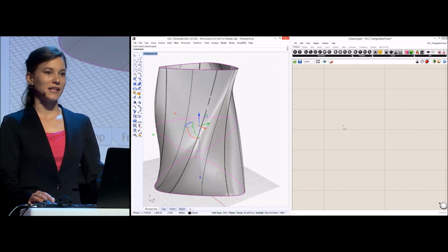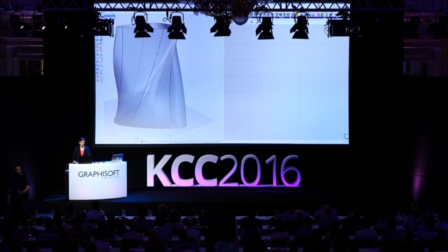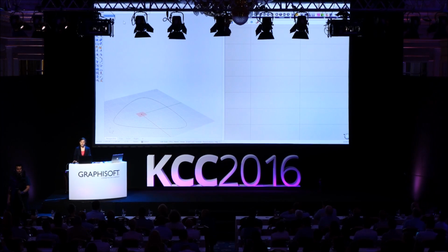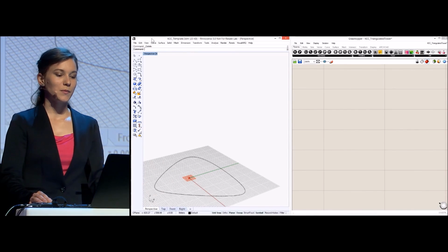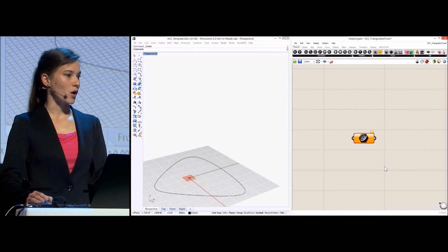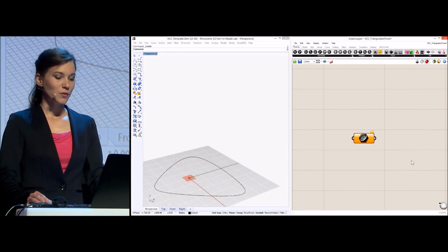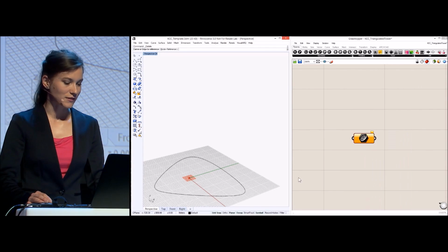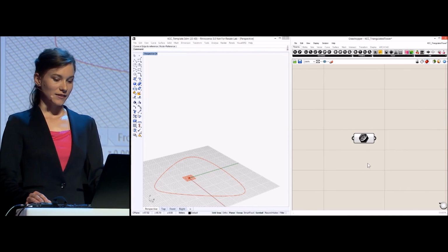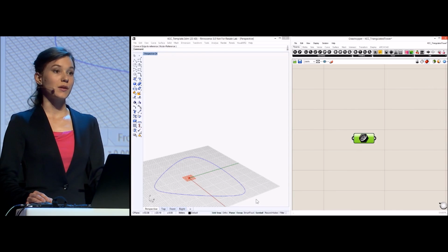Now, for those who are not familiar with this design environment yet, let me give a short intro. As an example, I will recreate the tower shape from scratch in Grasshopper. In Grasshopper, there are nodes, small boxes like this. These are the building blocks of the algorithmic definition. They can be containers or operations. With this one, for example, I can create a reference to the already existing Rhino curve here. So if I select this node, you will see this curve gets highlighted, indicating that the description of this geometry is now stored by this box.